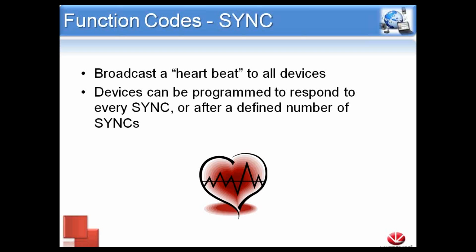I could have one always report back on every sync. As well, I could have a second device that only reports on every fifth sync. So you can set the timing using the sync. As well, one of the key benefits of CANOpen is when you do the request using the sync, you'll get all that information at the same time.